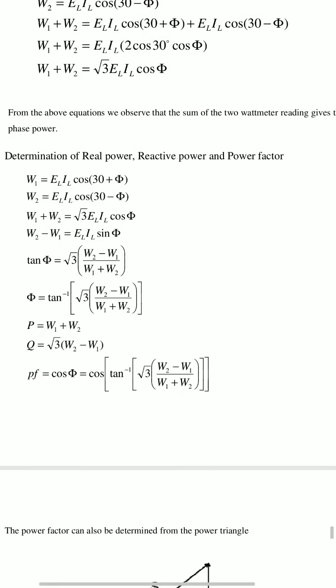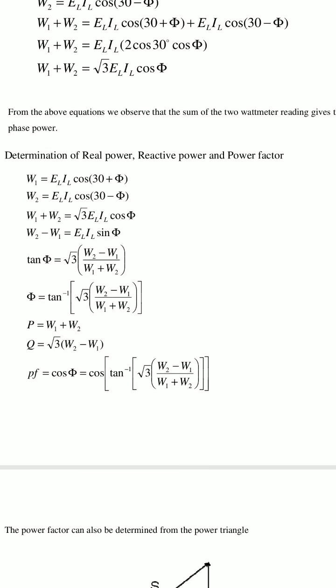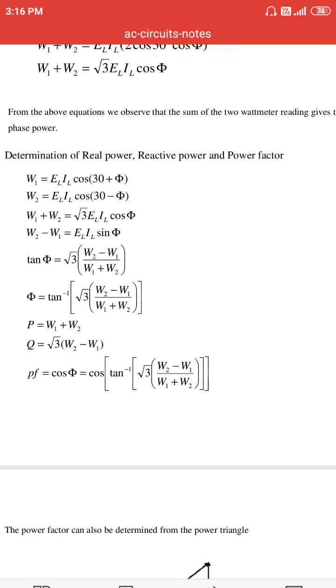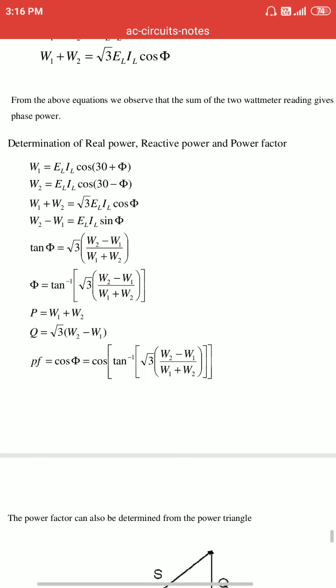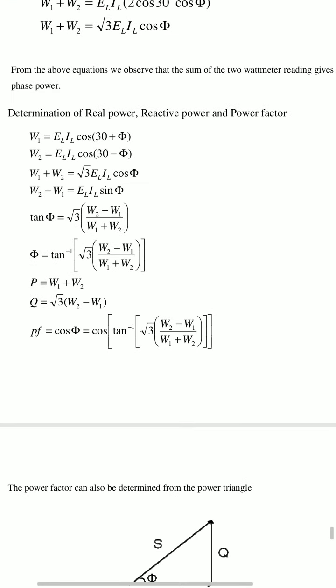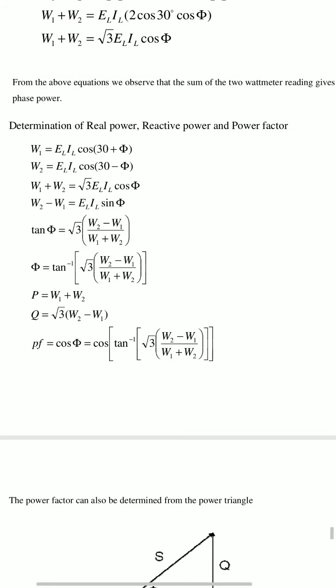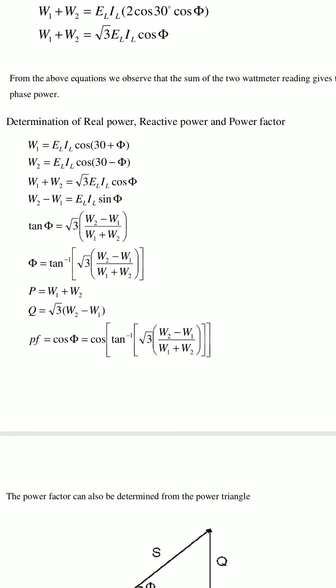Here, the determination of real power, reactive power and power factor. Here, W1 is EL IL cos(30 plus phi).